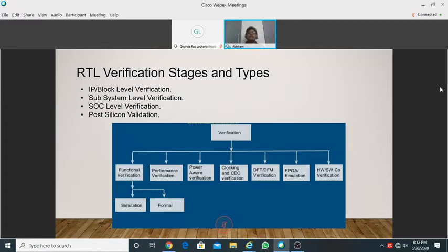That logic we can probe using product testers that have some probes, where you can visualize at what interface the data is being transferred, or at what interface inside the SOC the chip or ASIC is having an issue. So that verification also needs to be done, because of the 5 nanometer or 10 nanometer technologies. This step has also been very critical.